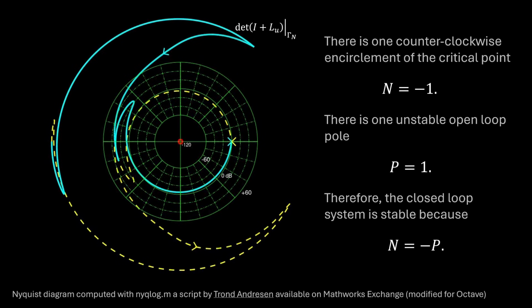We'd like to proceed from here with robustness analysis. But unfortunately, in contrast to the single input system, distance of the multivariable Nyquist diagram to the critical point is not a measure of robustness. However, singular values do provide a measure of nearness to instability.